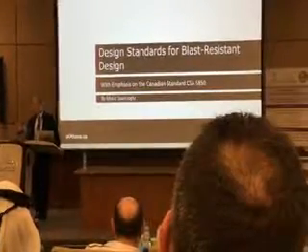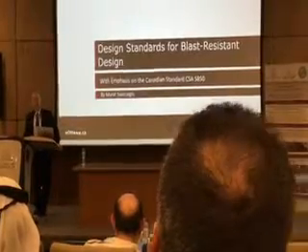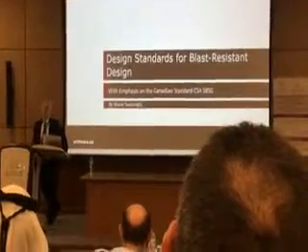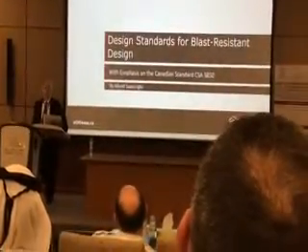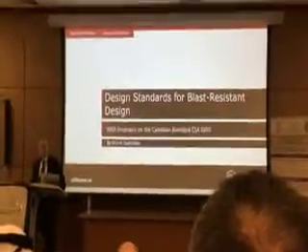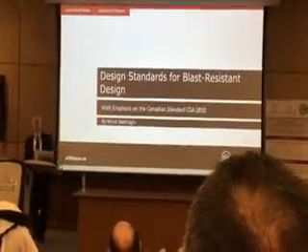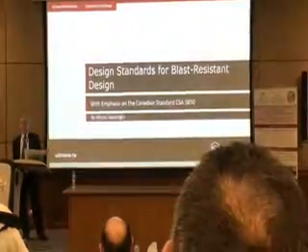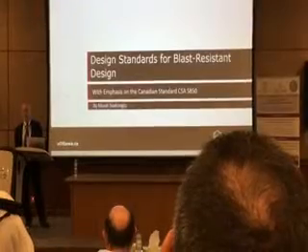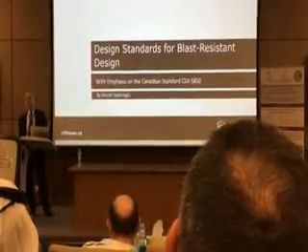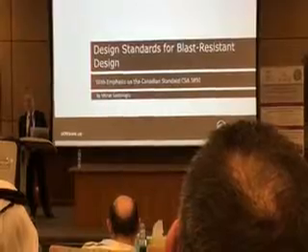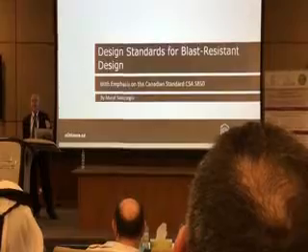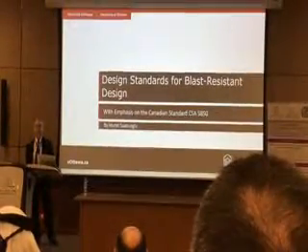But the curves that I showed you, the US Army curves, do not apply to contact charges and close-in explosions. The problem becomes very complicated. You have to use software like LS-DYNA or ANSYS to do computational fluid dynamics. And even there are challenges. How do you model the material? They have their own material models, and you have to trust them. But that's a different and more challenging problem. Perhaps the important answer to your question is that it affects the material rather than the member.